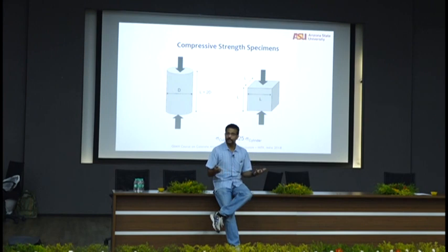So, does strength adhere to any of these conditions? No. Strength is not a fundamental property of any material. Strength is the resistance to stress. The material does not have its own characteristic behavior, it will just resist the stress. So for example, if you change the loading rate, your strength changes. You test faster, you get a higher strength. So basically if you make M40 concrete and you are not really sure it's an M40 concrete, you just tell the guy in the testing lab, just do it very quickly. Do it like an impact load, just crush it, and you will see 45 megapascal strength and you can make everybody happy. Right? So strength is not an inherent material quantity.